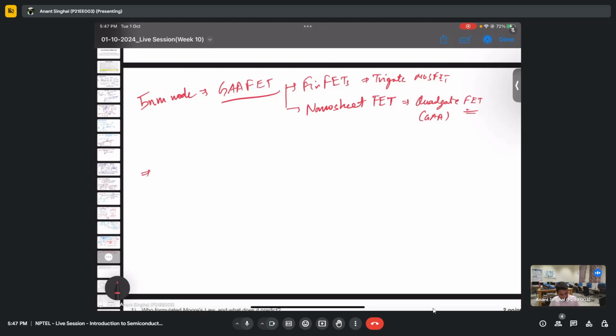Okay, so I guess currently we have the 4 nanometer technology node in iPhone 15 and 3 nanometer. Sorry, is it in iPhone 15 Pro and Max? So the latest technology currently in the market is 3 nanometer, and it is based upon FinFET. And next year, when iPhone 17 is launched, 16 also has the same 3 nanometer technology. They are claiming that they will come up with a 2 nanometer node, and that will come out for the first time from nanosheets. This is just for your knowledge.